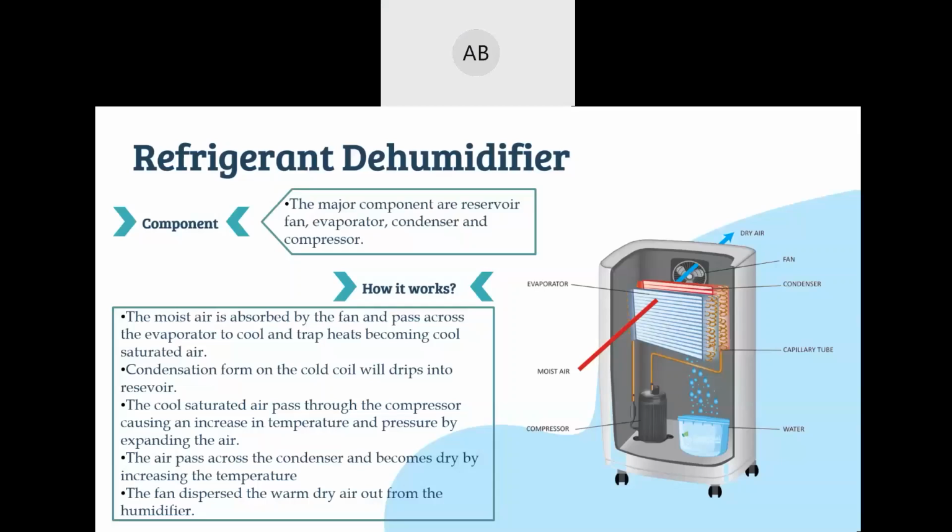For desiccant, it is perfect for large-scale commercial and industrial jobs where the temperature levels are lower. Meanwhile, the refrigerant dehumidifier is more efficient in small spaces where the temperature level is higher. Also, refrigerant dehumidifiers are more recommended if the space has a noise requirement, because this unit is much quieter than desiccant-based dehumidifiers. That is my answer for your question.